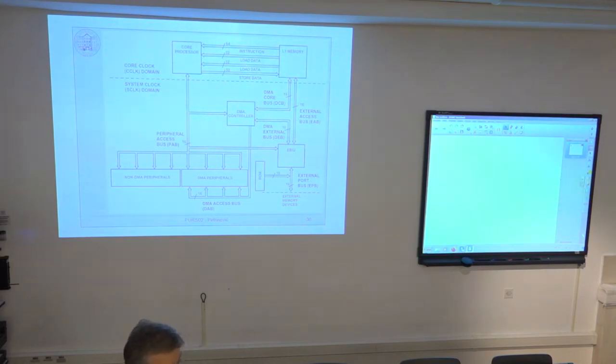So it has several channels. Each of those channels would have a counter, it would have the pointer, and simply it will take the value, write to memory, to the pointer value, increment the pointer, and check whether the counter has come to the end. If it did, only then it will generate an interrupt request.